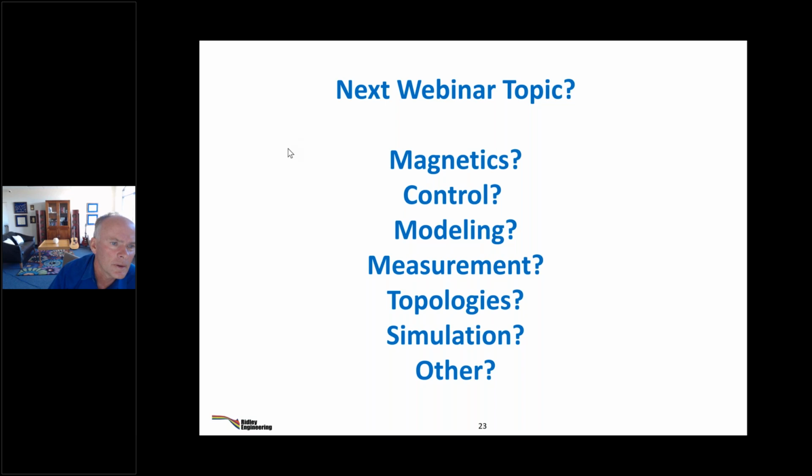DAB, is it attractive at low line voltage compared to LLC? Well, DAB is a player as well. Be aware if you do dual active bridge, you are in digital control. That's it. But there will be issues with the DAB as well. I mean, no converter is perfect, otherwise we'd all be using the same one. Remember now, as I just showed you, the old converter from 50 years ago, a forward converter, it's still competitive. So there's no need to do these fancy things, but you should know what you're getting into if you try.